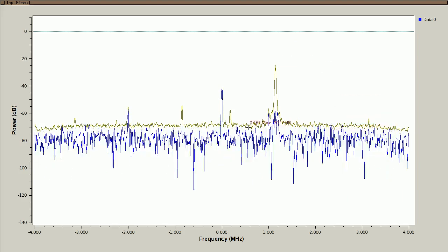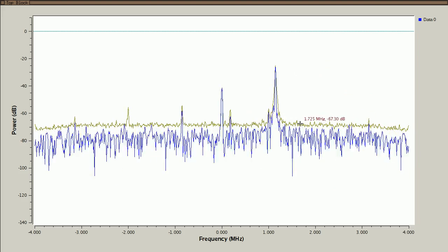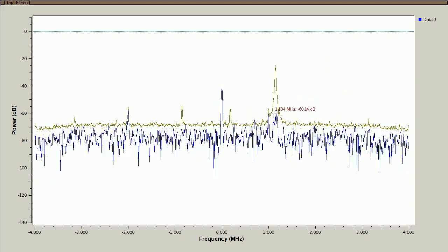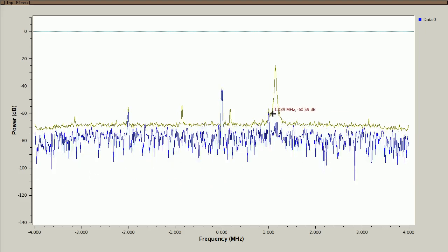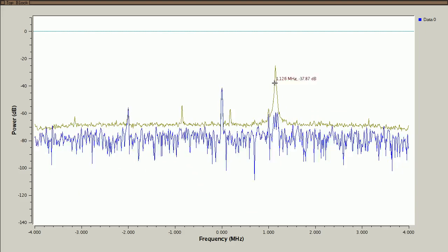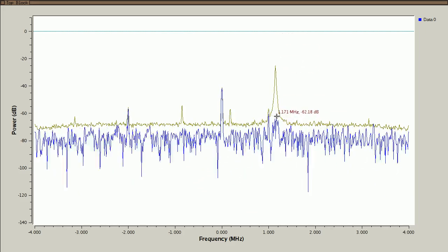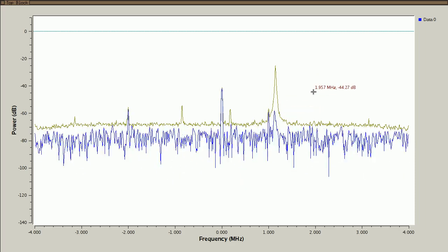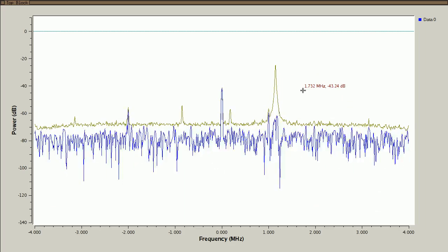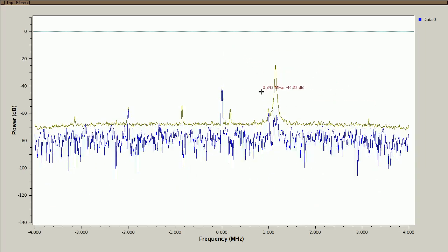And we're not transmitting that broadband noise anymore over 2 megahertz of bandwidth, although we are transmitting broadband noise over this 100 kilohertz of bandwidth right here. Even between the intentional bursts, we are transmitting a little bit of noise. So we're definitely being a much better neighbor on the spectrum than we were, although it looks like there may be some ways that we could still be a better neighbor yet.